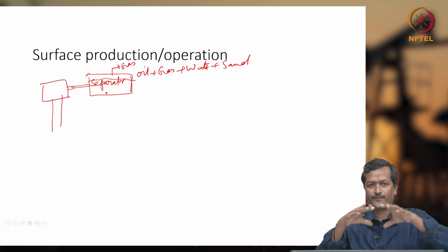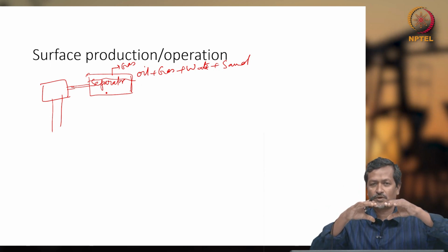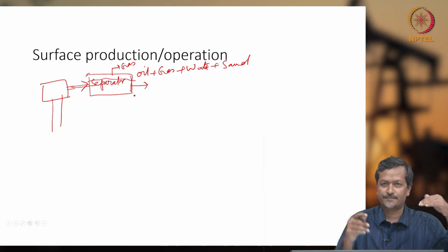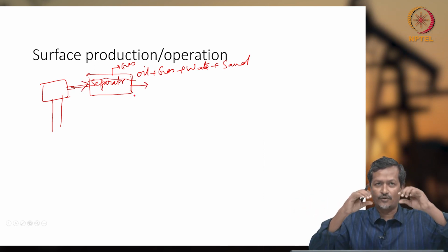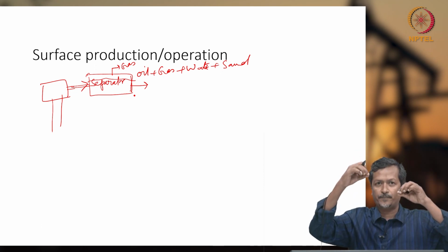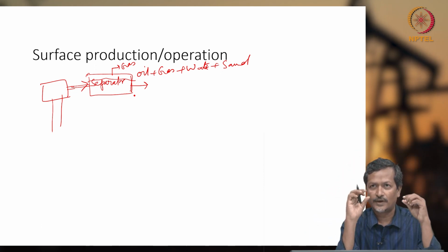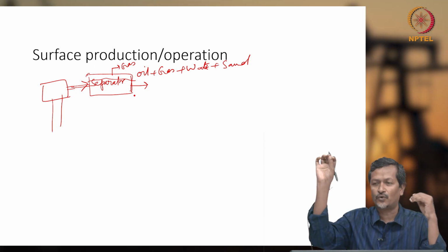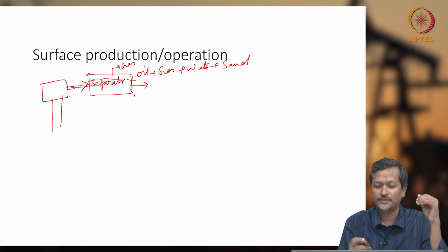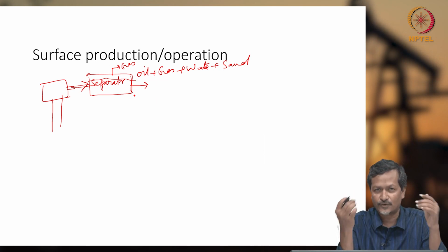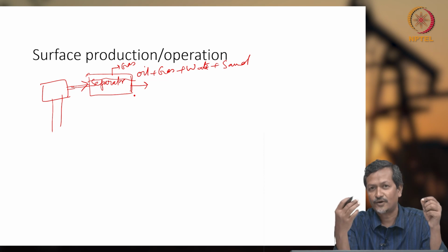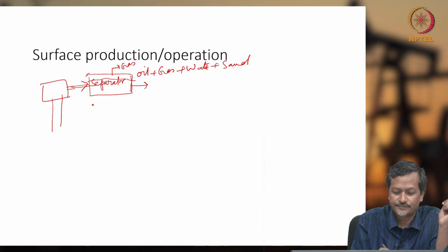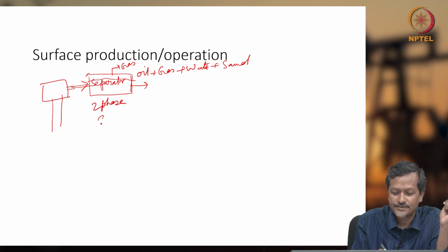In pressure vessel, if you have one pressure vessel, you put oil and gas through inlet pipe, and there will be exit pipe for oil, and on the top of the vessel there will be one hole. So there hole will have one mist extractor, and you will get gas, because this gas is lighter weight. So gas will be escaping from the top hole. From the bottom or near bottom hole, you will get liquid. Liquid means oil, water. A sand also can be there, or sand can be settling at the bottom. So this is two-phase separator.